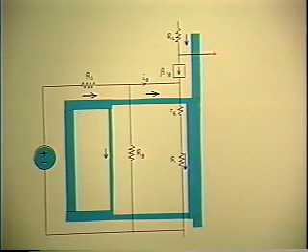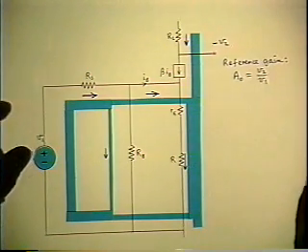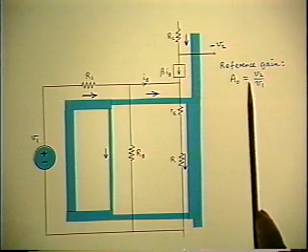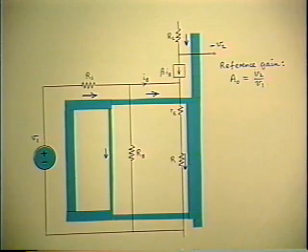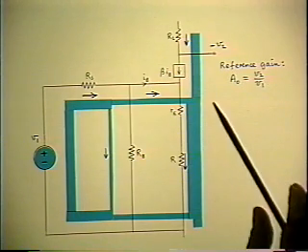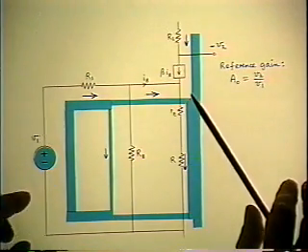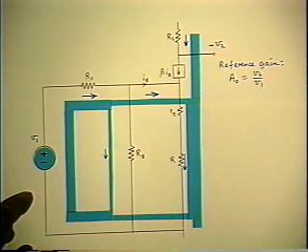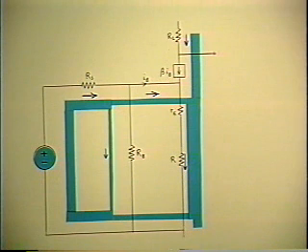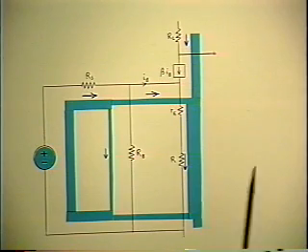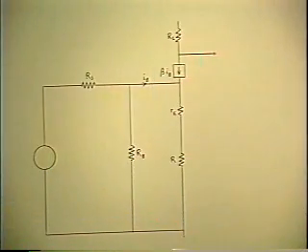Okay, and the result of this calculation is the gain A0, V2 over V1, which we did to begin with, and it came out to be 6 dB. Okay, that's the reference gain, the gain of the circuit before we've made any changes. So now what we're going to do is calculate the two driving point impedances at the place where we're going to add the extra element.